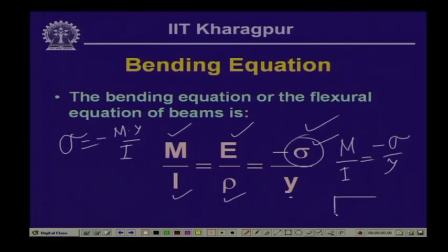If we take the segment, the positive bending moment in the beam was like this, wherein this type of moment causes compression at the top and tension at the bottom. Because of the bending acting in this segment, the bottom fibers undergo stretching, which is tensile, and the top fibers undergo compression, which is compressive.